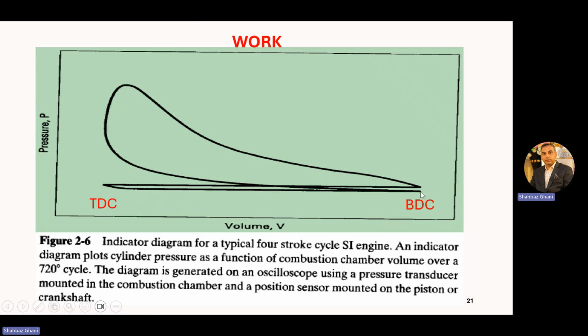SI engine. Now the compression stroke starts. The second stroke, the piston is moving from BDC. It is compressing all the intake volume. Then volume is reducing, pressure is increasing, and it reaches the point here. Somewhere here, your ignition starts, and you get the combustion. It's at constant volume. Remember the term which we have used in the example, constant volume.